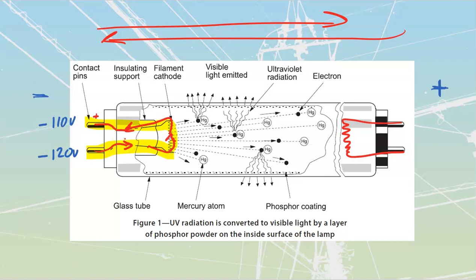That current flow that is traveling through the cathode is going to give us what we refer to as our cathode preheat. If you have worked in the industry long enough, you'll be familiar with the fact that fluorescents sometimes struggle to get lit anytime that we've got too cold of a temperature. And the reason for that is that they need to have a certain amount of heat on the inside on their cathode. The cathode is going to be a coil.